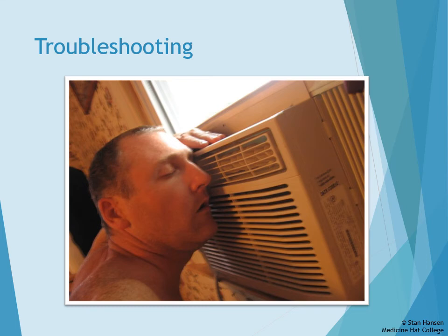Go up to the thermostat and remove the cover and check the voltage between the Y and C on the thermostat. If you have your voltage there, that indicates either a bad wire or bad connection between the thermostat and the furnace. However, if you do not have that, it might be a bad thermostat itself. But make sure you have voltage coming into the R and C terminal at the thermostat.